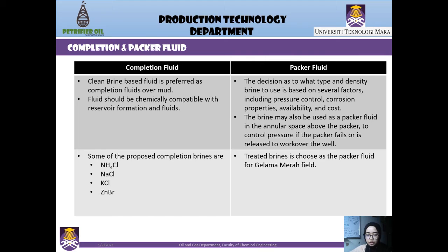The next one is the packer fluid. It is advisable and preferable to use the treated brines for the Glamour Merah field. This selection is based on several factors including the pressure control, corrosion properties, availability, and the cost of the fluid.